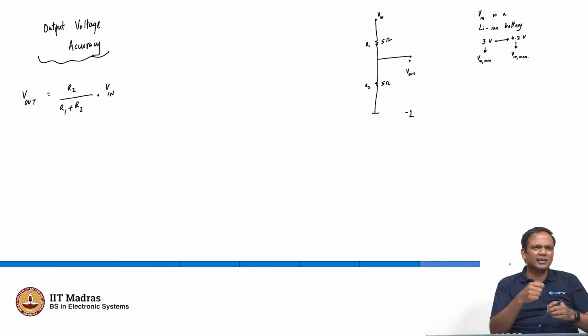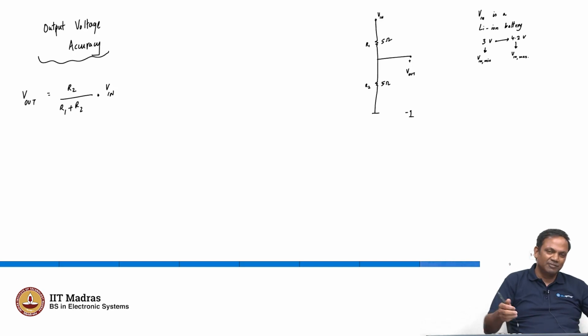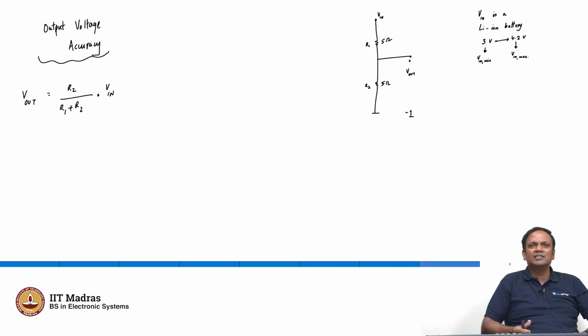That is important because, again, I told you that this block can take between 1.2 and 2.1 volt, which is a very wide range. You ideally want to give it as kind a voltage as possible, or operate that subsystem in its sweet spot.